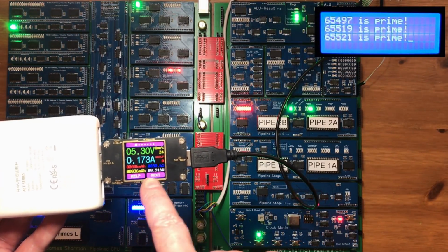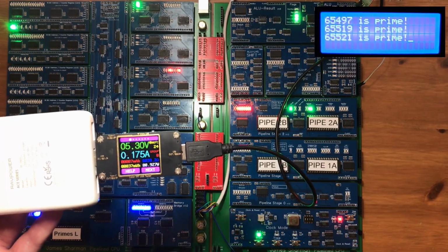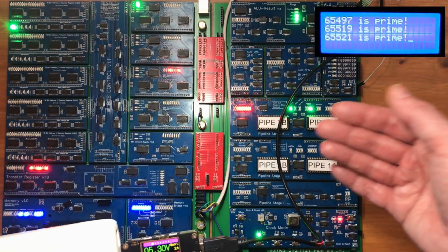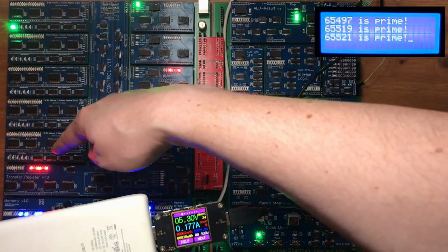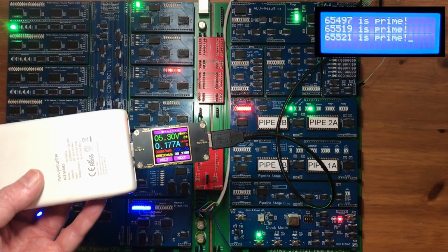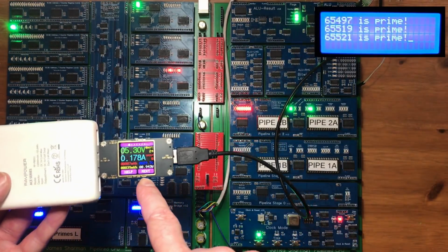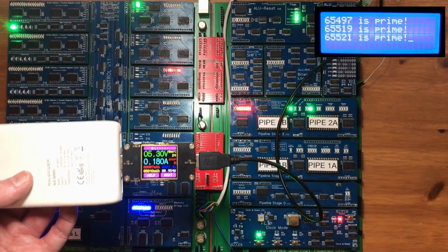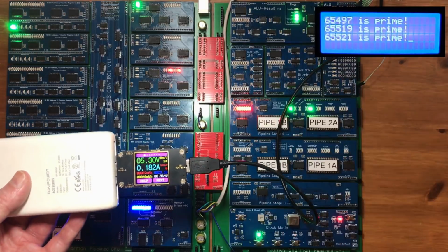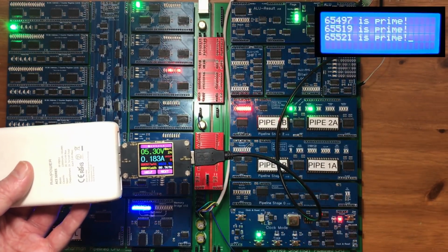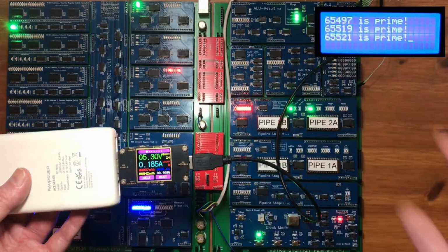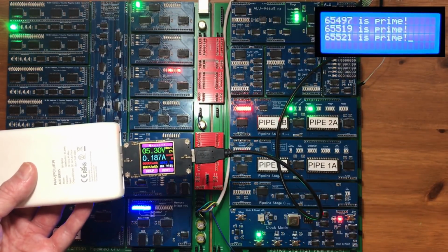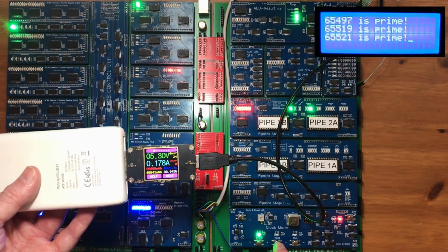Okay, so this dropped down quite a lot when I reset the processor, and the main thing that changed there was all of these address registers reset to 0. So I think that's letting us know that a significant amount of that draw is actually the LEDs. So I might actually write a piece of code at some point which turns on as many LEDs as possible simultaneously, because that might just be the primary thing.